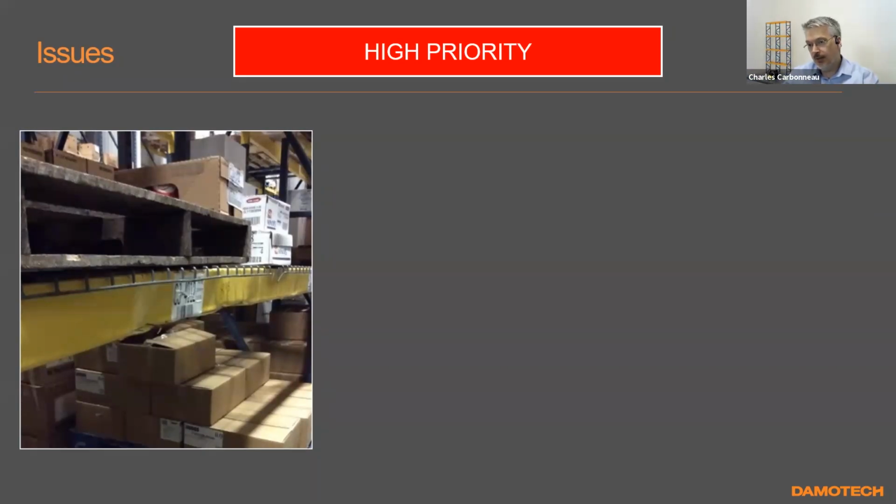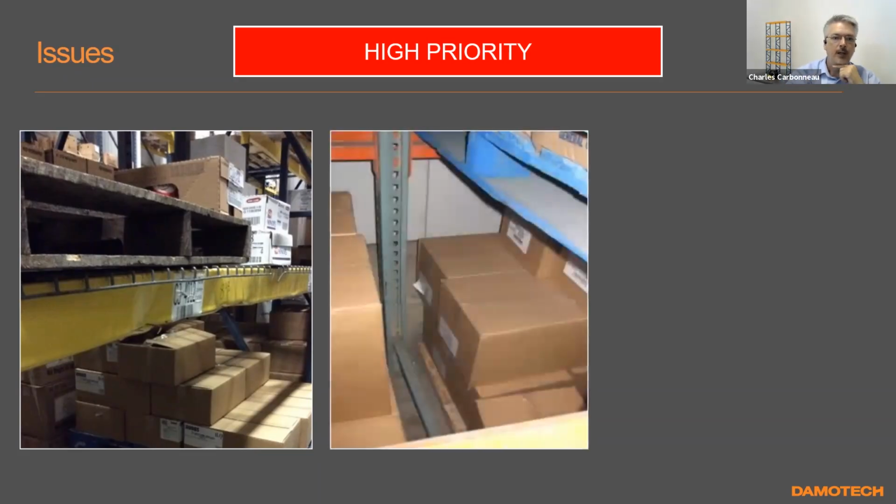What we don't see in that picture, and part of the reason why it was high, is that it's been deformed by raising it, probably impacting it. And you've got to go and see the connectors at both extremities, because at one point they are affected. And it's hard to see, but sometimes the column on which they're attached has been affected. The holes on the side have been strained laterally because of these stresses.